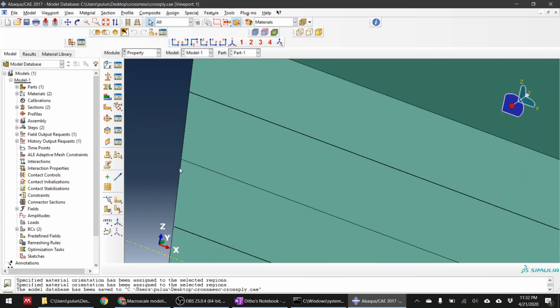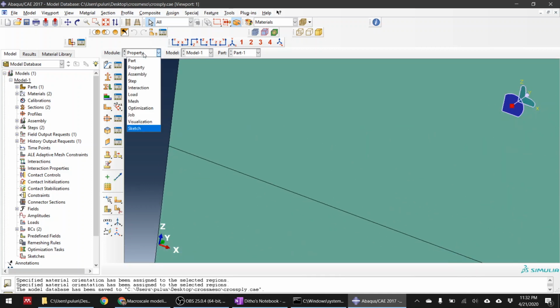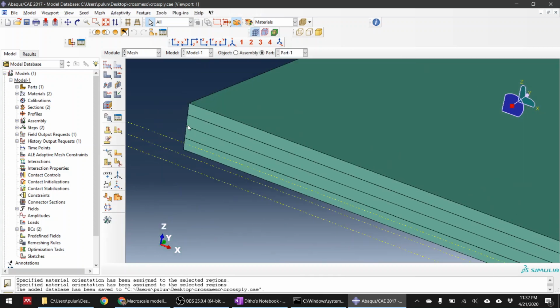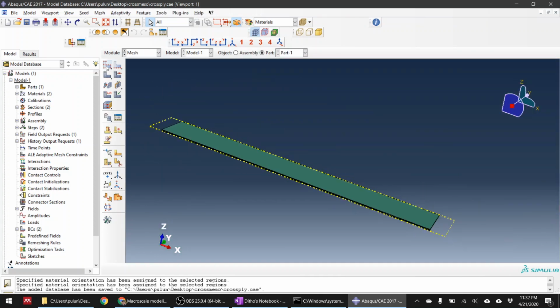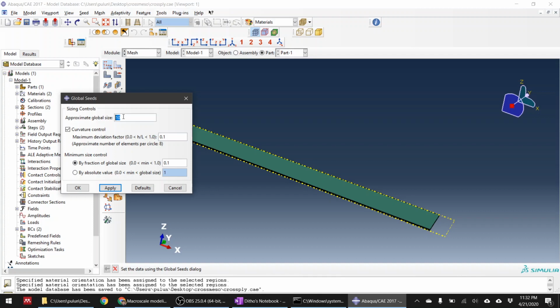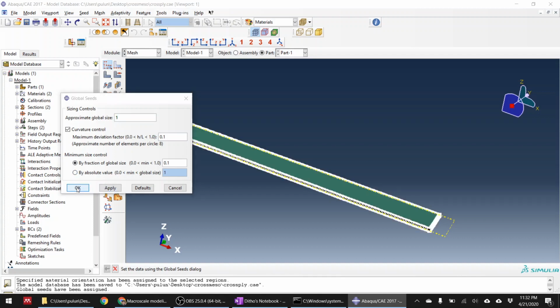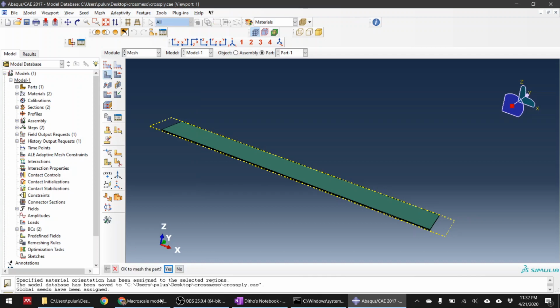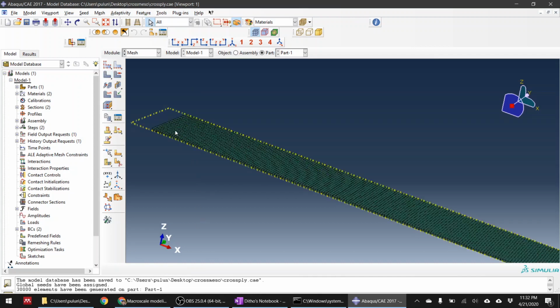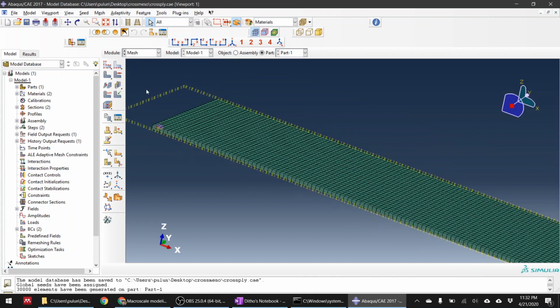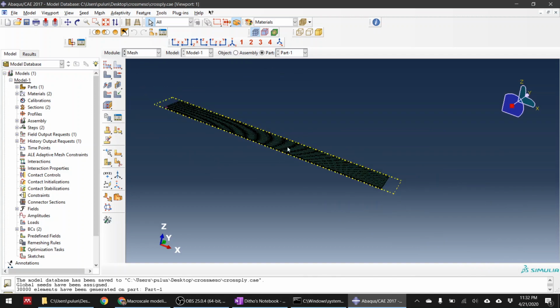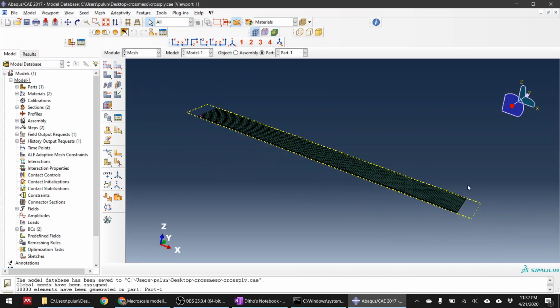The middle you don't have a cohesive element because it's between 90 and 90. Okay, now you do the mesh. So create mesh. I always recommend for this coupon task, you always use 1 millimeter. That's the recommended size for me. It's nice, right? And these days computational tools like your laptop are very good, quad core, 8 core, so you don't need to worry about that.